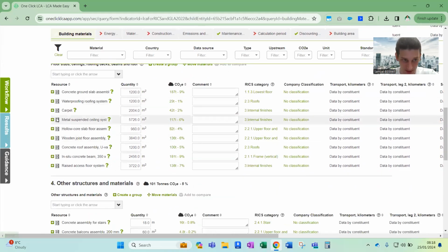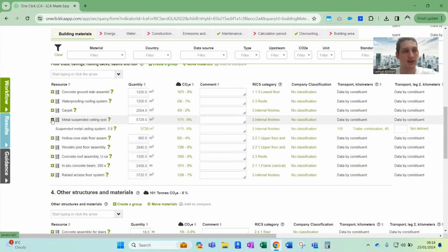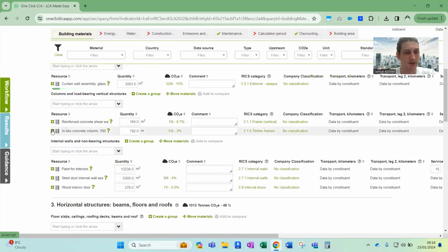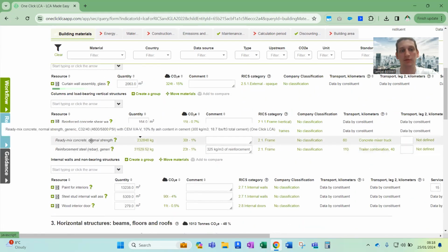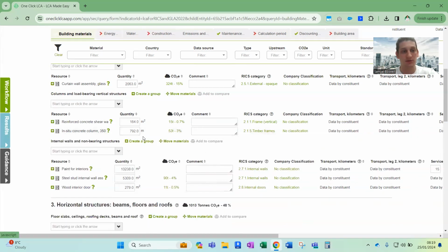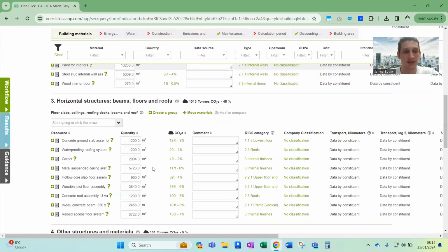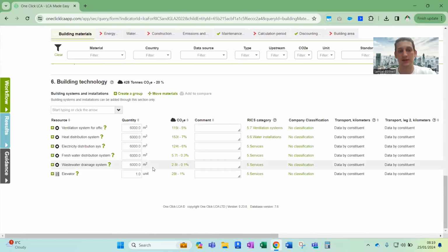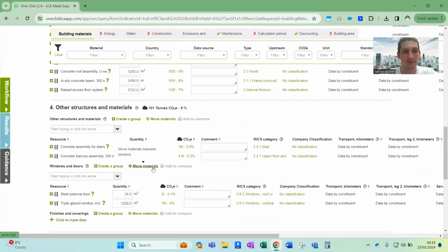And you can see they've got this icon here, this plus symbol. And if I click on that, well, actually, that's not the best example, but maybe in situ concrete columns, you can see they're made up of multiple materials, and the quantities reflect the dimensions of the entirety of that construction. So this is really how Carbon Designer 3D works, is it's applying constructions to all of the different building elements, and then you can just simply import that back to the main software.